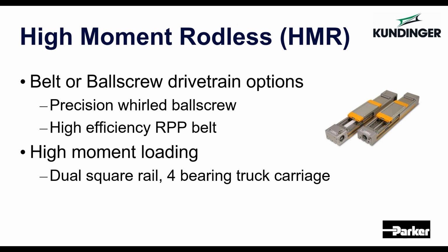It does utilize the same flexible mounting type features as the OSPE glider bushing variants. You have the dovetail grooves, or dovetail mounting on either side and on the bottom as well for side mounting, or if you just need to put the mount somewhere else due to a space constraint. And the end caps on these units are actually drilled and tapped as well for some type of end cap mounting, or if you were to put this into, say, a vertical application, mount the carriage, fix the carriage in place, and use this in a carriage to carriage moving beam type actuator, you could very easily mount end effectors and end of arm toolings on the end of the unit as well.